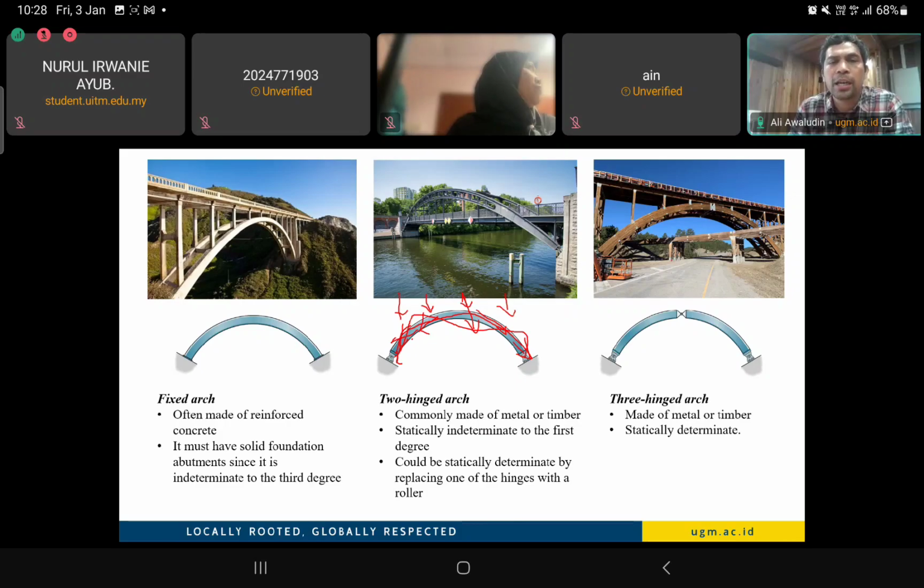My postdoc. Actually, we are mostly dominated by the normal force, which is a compression member. But here we have some bending moment. As we saw earlier, we draw the bending moment. For example, if I cut down this one, I'll see this is the cross section of the arch we are mentioning. We have the normal forces, which is mostly always compression, but we also have the bending moment.